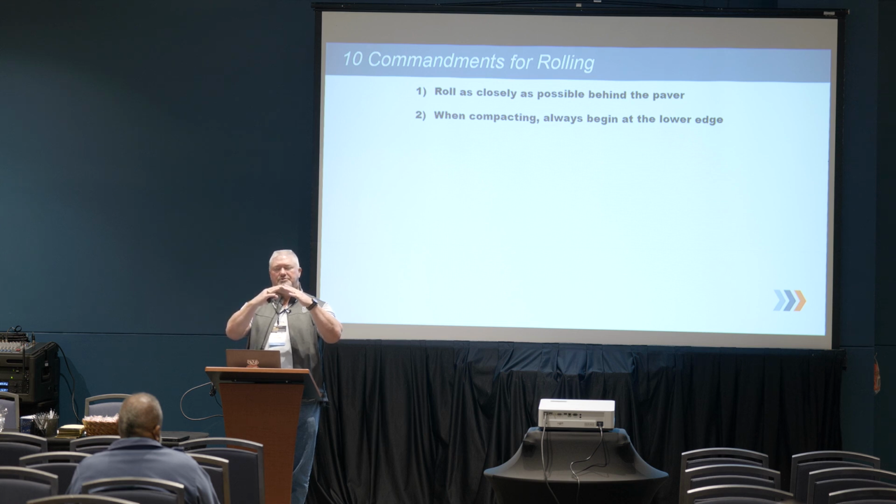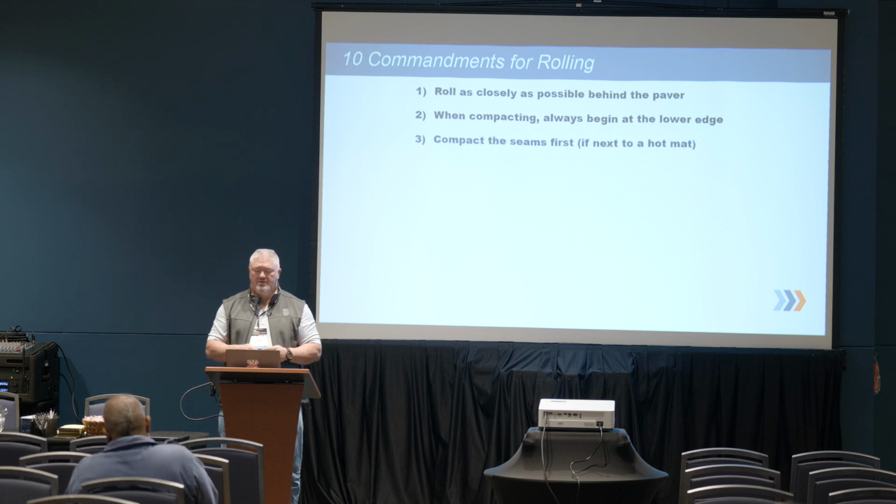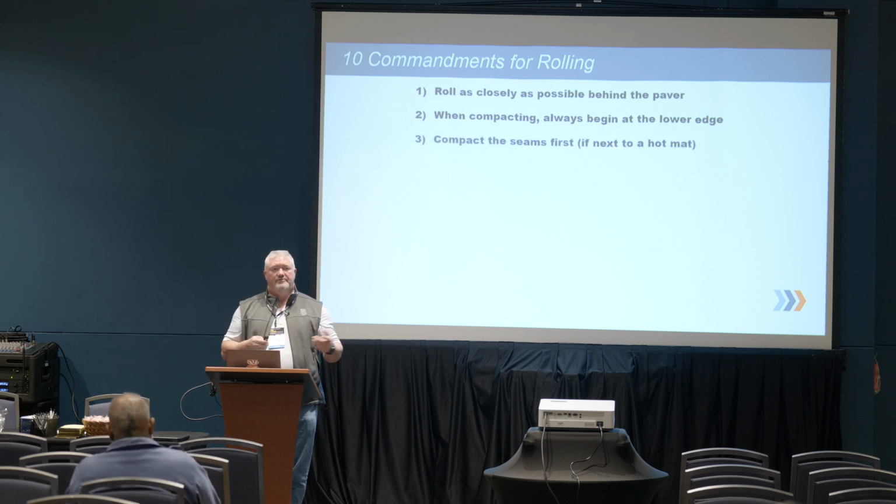And when I compact that joint, by the time I'm ready to compact it, that hot mix has warmed up that cold joint. So when I do compact it, I get a better bond at the joint. So I want to push the material against gravity up towards the joint. Some people say, well, I got too much material there and it rolls over. That's just an adjustment with the joint matcher on the screed. Finding that fine-tuned adjustment. The only time I go joint first is if it's next to a hot mat. Then I want to go back down to the low side, still bring everything back up to the joint.